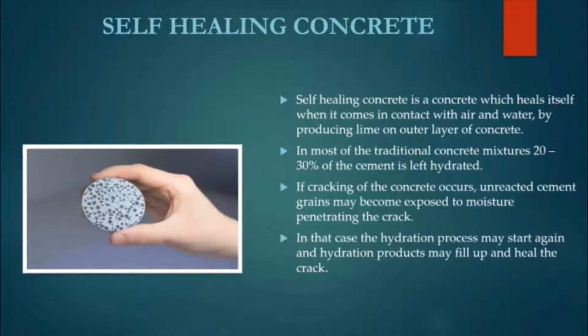It will biologically produce limestone to heal cracks that appear on the surface of concrete structures. Selected types of bacteria, along with a calcium-based nutrient known as calcium lactate, and nitrogen and phosphorus, are added to the ingredients of the concrete when it is being mixed.